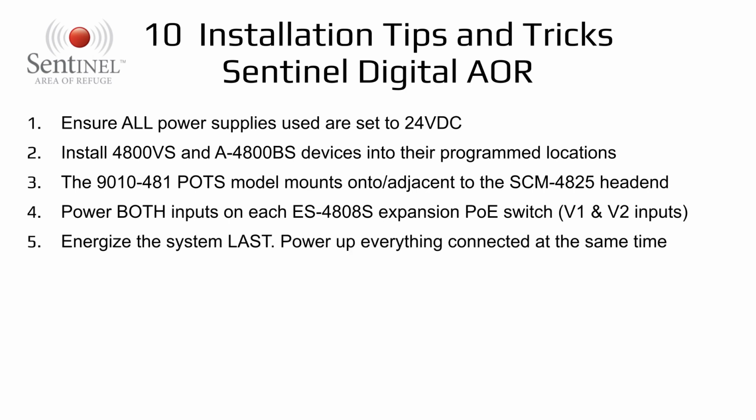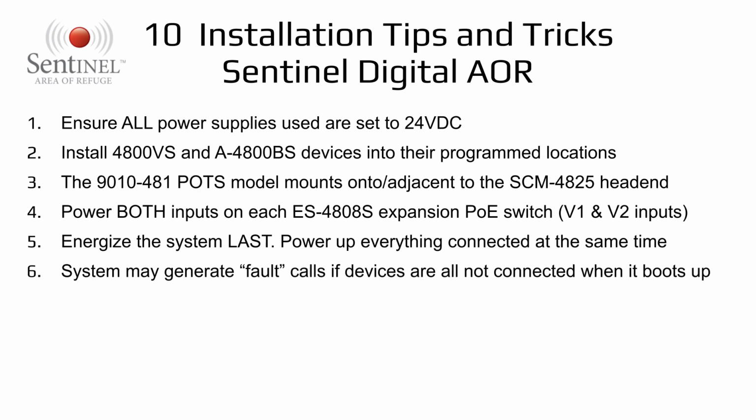Number 5, energize the system as the last step. You always want to mount your back boxes, install your devices, make your network and other cable connections, and as the last step, you just want to energize the system and all power supplies. Number 6, once your system fully powers up, it may generate some fault or error calls on the system. Fault or error calls on the system are within normal operation and are designed to bring attention to device or connection errors.